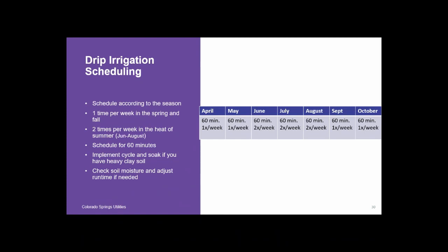What I mean by that is you want to make sure that your lawn or grass areas are being watered on a separate program from your drip irrigation, because if drip irrigation is on the same program, it's running as frequently as your lawn irrigation. If we're watering our lawn right now in the heat of the summer in June, we might be watering 3 days per week. We definitely don't want to water drip irrigation 3 days per week.